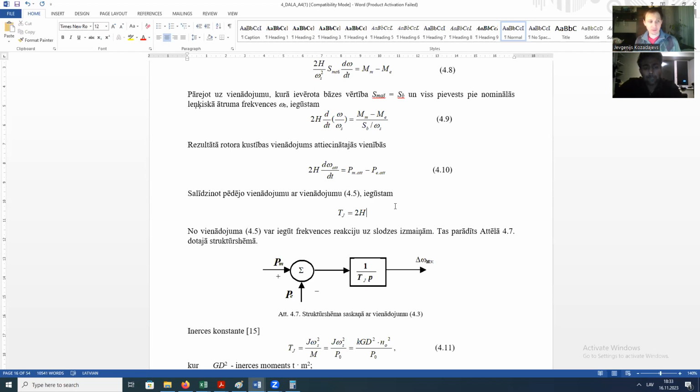power systems, it is very important to understand the speed of processes in our power network. Of course, it is clear that if we have a huge drop of generation, for example, the speed of frequency decrease will be much higher than if we have a very little deficit. So the amount of deficit, how big this deficit is, provides a different speed of frequency fluctuation.